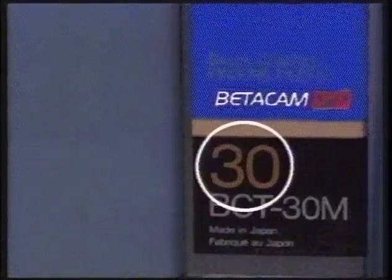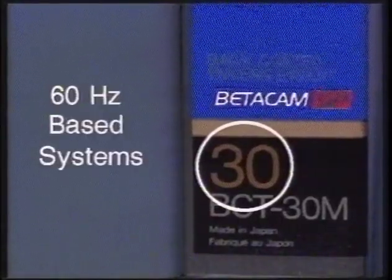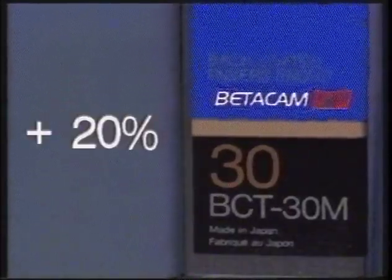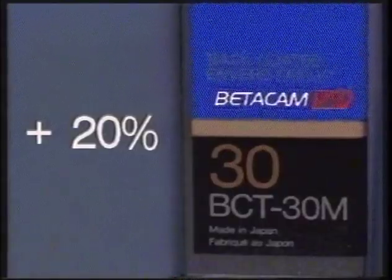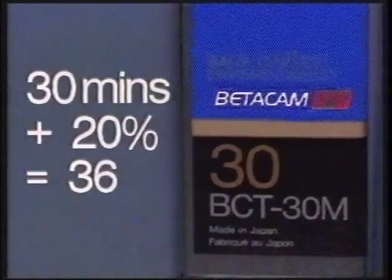The tape timings actually refer to 60 Hz based systems. In fact, with 50 Hz machines, that 10 Hz difference gives 20% more running time. So marked 30 minutes will run for 36.